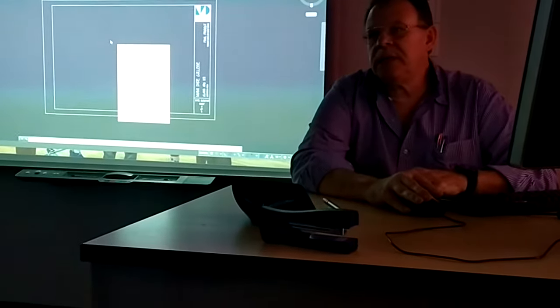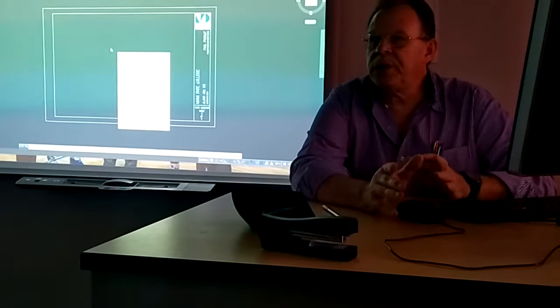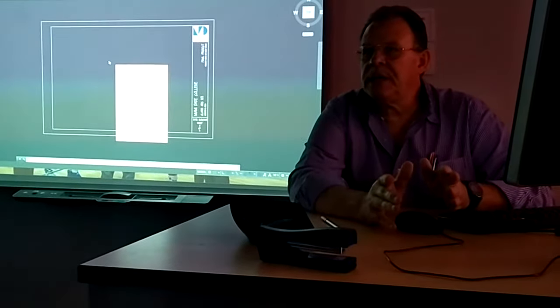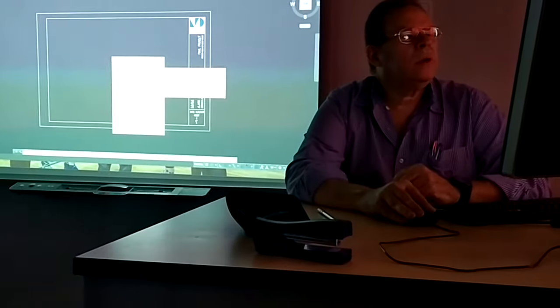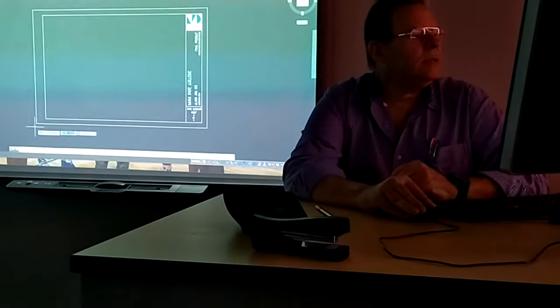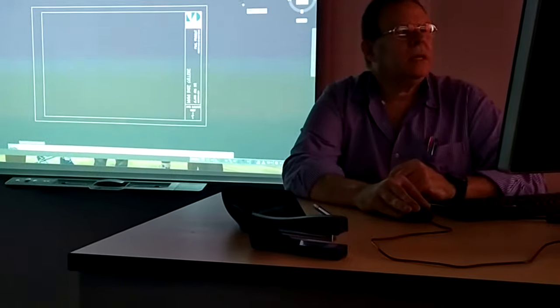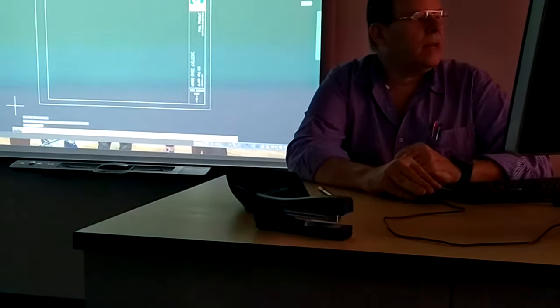Remember, Paper Space is another space that you print. You plot everything in there to any scale that you want. Okay, so clipboard, copy with base point. This is going to be my base point, and then I'm going to highlight the entire block, right click, enter.